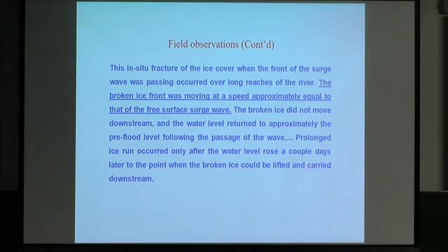And the broken ice front was moved at a speed approximately equal to the free surface surge wave, which is the wave speed of the shallow water wave, square root of gH, or square root of g times the depth of the flow, and so on.